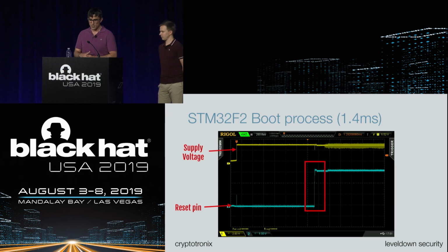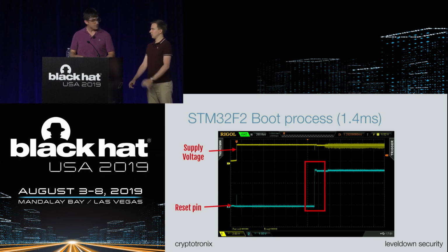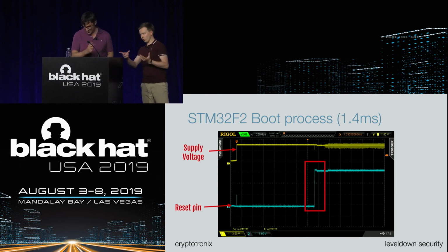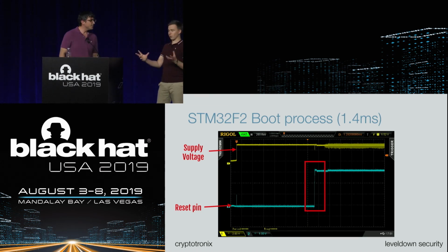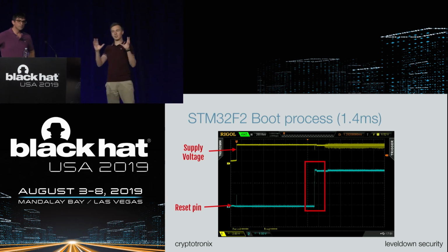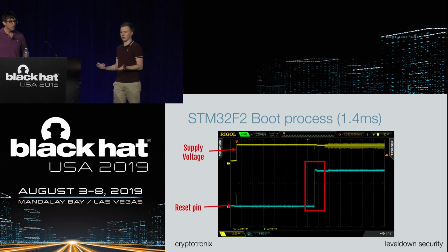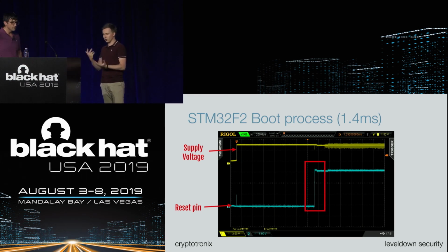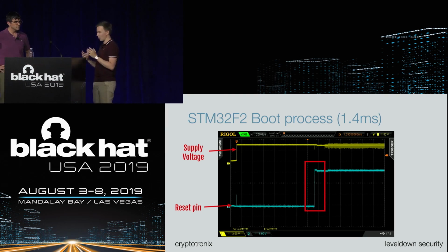Here we also have the supply voltage and a reset pin. One of the most important things is the problem we had with this chip: the power on takes different amounts of time every time you boot it. Basically the PLLs and so on need to synchronize, and some capacitors charge up or whatever.